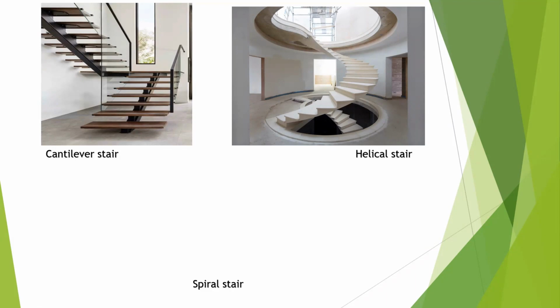And I'm not going to recommend a reinforcement that is less than 16 mm at 200 mm center to center, top and bottom. It's going to be doubly reinforced.